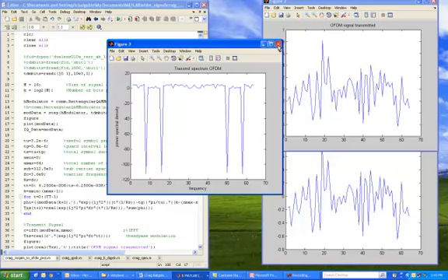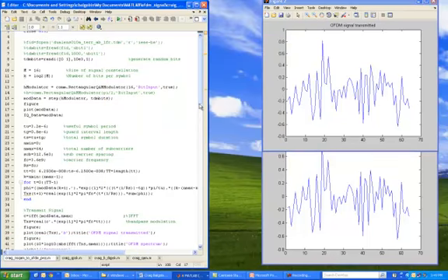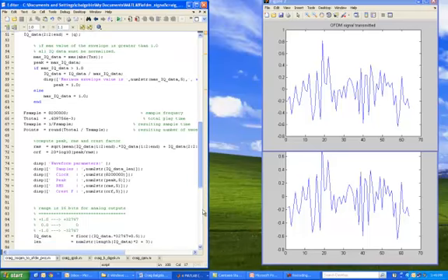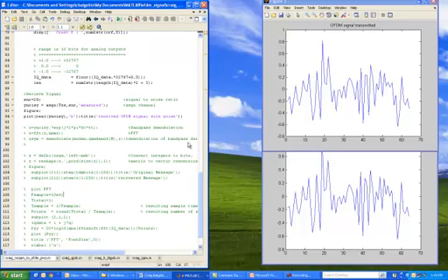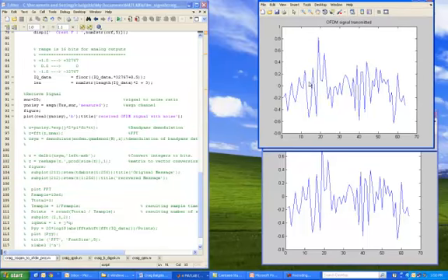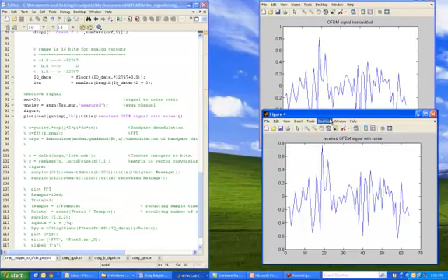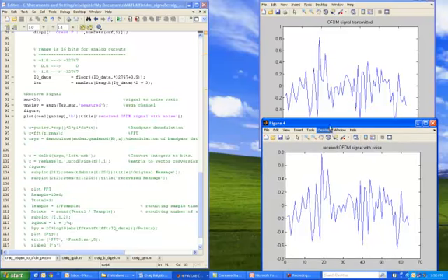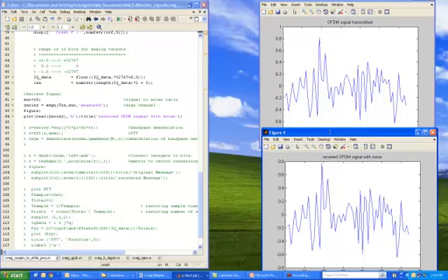And what I was able to do is I passed it through an AWGN channel, a noisy channel, adding noise. Here I defined a signal to noise ratio. So for this simulation I did a signal to noise ratio of 20, which is very good. So if you look at the signal transmitted and the signal received, it's pretty identical in a 20 dB signal to noise ratio channel. If I lower this channel to, let's say, 8 dB,